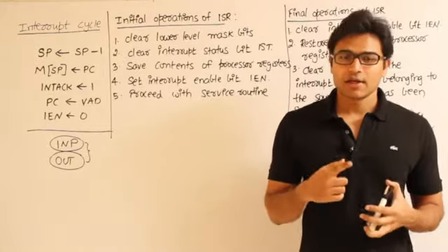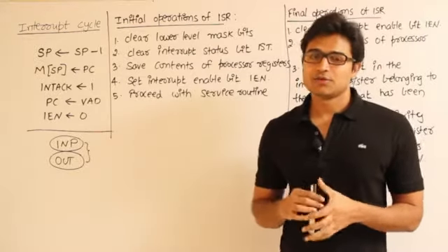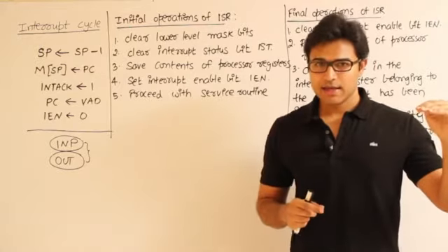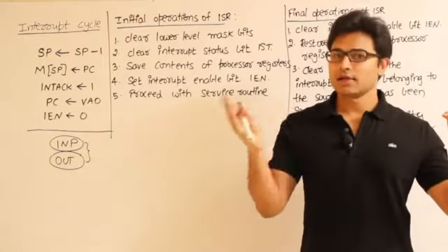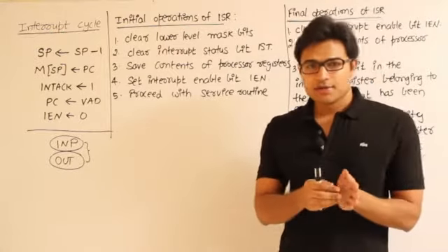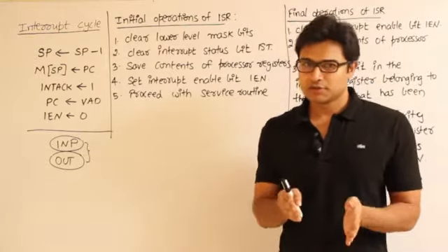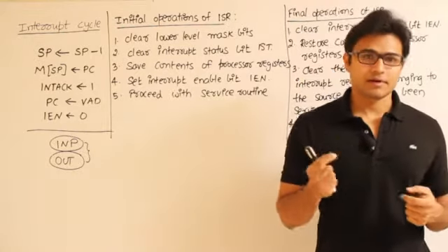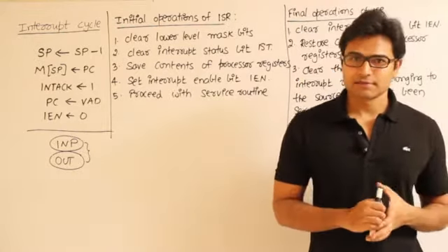But after that, once the interrupt has been raised, you should stop executing your program, which means whatever program you have been executing, you have to stop it and deviate from that. From there the overhead starts, right? So what happens first whenever you get the interrupt? Let's say you have completed executing your current instruction. After that, again you are going to get T0. Along with T0, if the interrupt flag is also set, then instead of triggering the instruction cycle, as I told you, we'll trigger the interrupt cycle, right? If you remember, that is what we discussed in the design. Instead of entering into the instruction cycle, we are going to enter into the interrupt cycle.